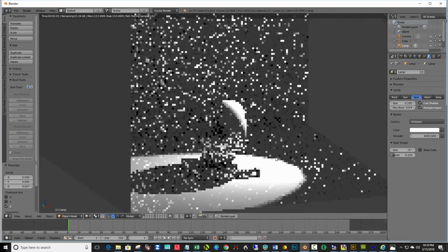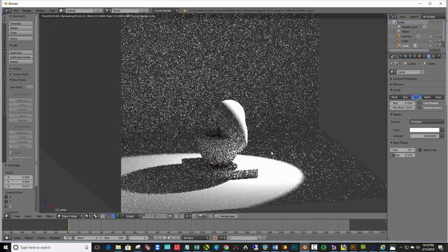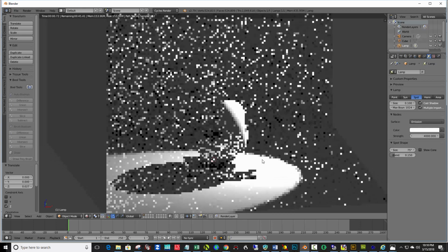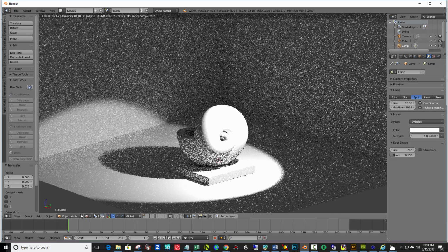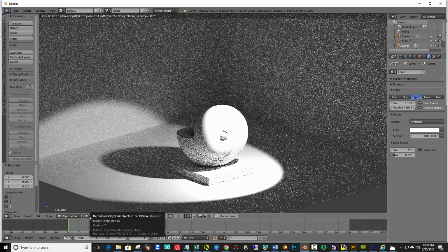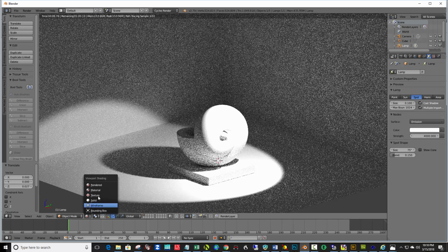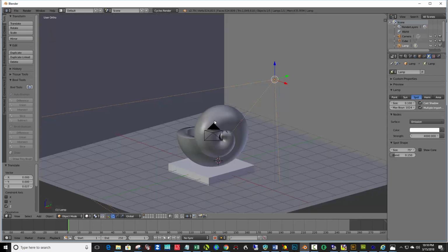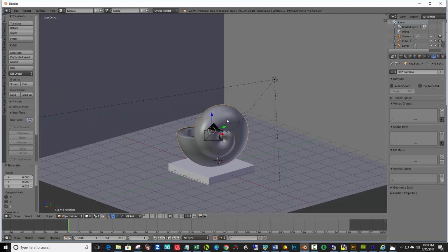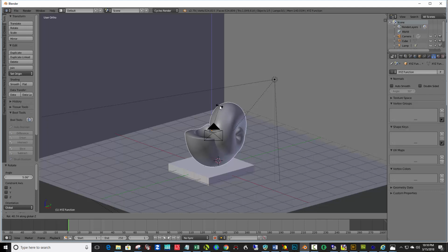Rotate this around. I think I'll rotate that. So I'm going to click back here on solid mode. Right click on the object, hit R for rotate along the Z axis. R, Z, and I want to see more of this face here.